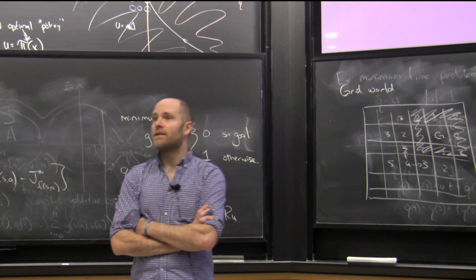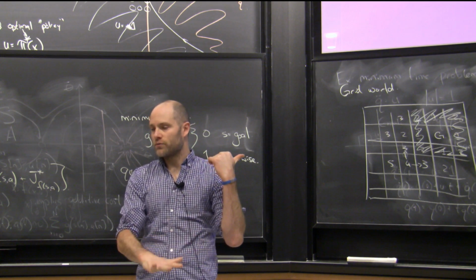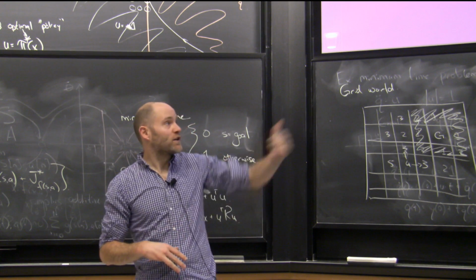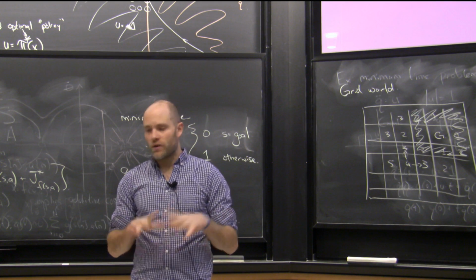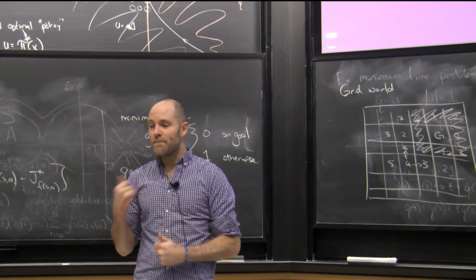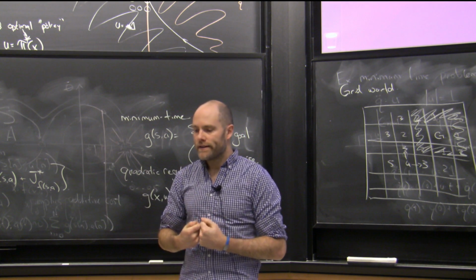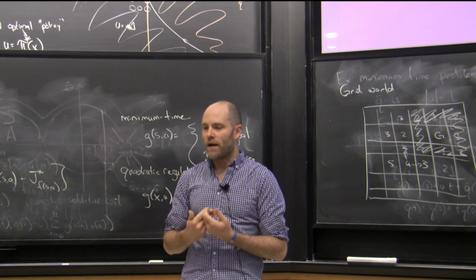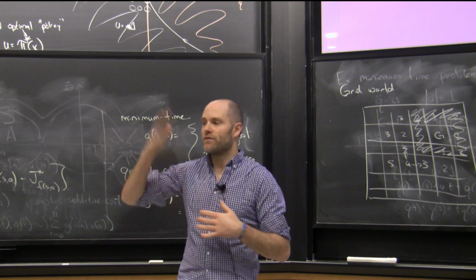So I can give guarantees. This version, because of my discretization, I don't have strict guarantees about the continuous system. I could have run that and it would have just gotten stuck somewhere because the discretization was too coarse. But there are versions that are better, more continuous, that can give guarantees. The type of property you might want is something like guaranteed cost control, saying that no matter what happens within some bound, I'm guaranteed that the cost I receive will never surpass some amount.